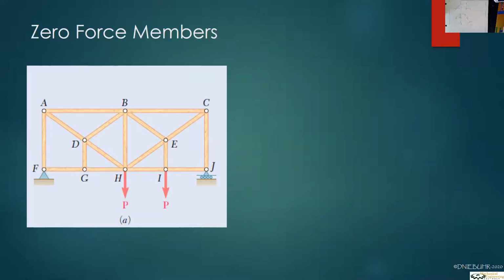So this one is a little trickier because it kind of defies what you would think should happen in this type of system. Now remember again that when you're looking at this truss, you only have vertical forces. There are no horizontal forces. So it's safe to say that the reaction at F in the X direction is 0. So if that's the case, then FG probably can't really be there. And so that's probably going to drop out, but let's look.